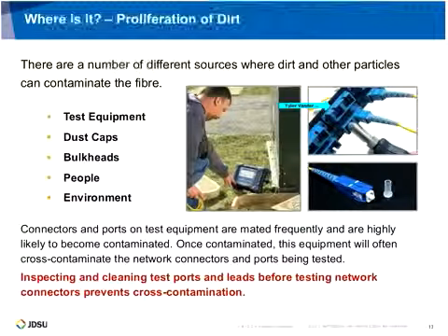I have a little microscope that came with the kit I bought with my fiber connectors, and I always check before plugging it in. But I want to caution you on that, because there are two sides to every connection. If you're only checking the end face of the connector you're plugging in on the male side, the patch cord side, you're missing the other half of the connection.